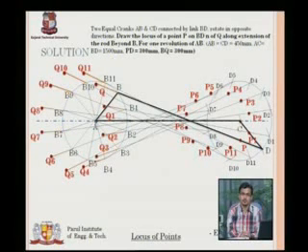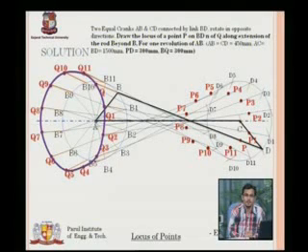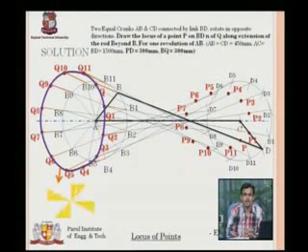So now what will I do? Now I want the locus. So what will I do? I'll connect all the points of Q first. From Q1, I'll go to Q2, Q3, Q4, Q5, Q6, Q7, Q8, Q9, Q10 and Q11. So here we go. We got a curve. It does not look like an ellipse, it does not look like a circle, but it is a smooth curve. That's what you have to make sure. It should not have edges. So this is my required locus of point Q.